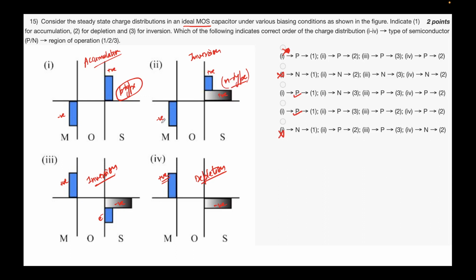And you can also understand it this way: if you apply negative potential on the gate, on the metal here, it is going to repel away all the majority charge carriers, the n-type, right? And positive charged core or lattice atoms will be exposed. However, if you apply an even greater negative bias, the n-type semiconductor will become inverted, and you will see the minority charge carriers, which are holes, get collected on the oxide semiconductor interface.